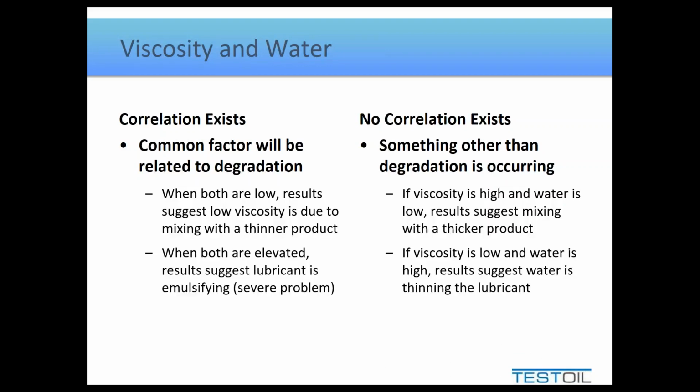If it's the opposite and water content was high but the viscosity was low, then we're probably looking at the fact that water, being thinner than oil, is actually thinning the lubricant, yet we're not forming an emulsion. So it's significant water contamination, but it doesn't have an end result of an effect on viscosity, which means that if we deal with it soon, we can probably mitigate some significant problems.